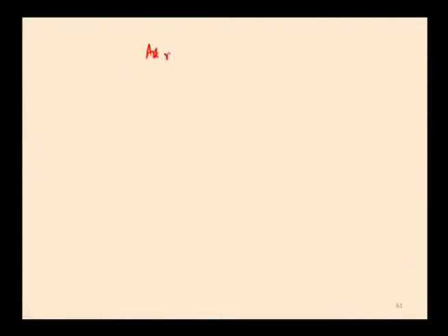AST required is 553.59 millimeter square. So, I am going to use 10 mm diameter bar.